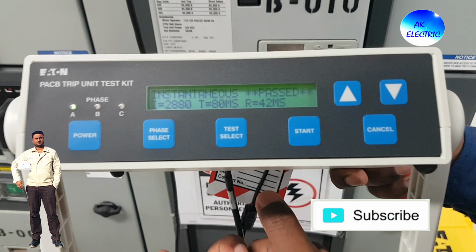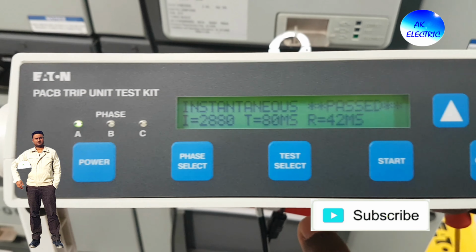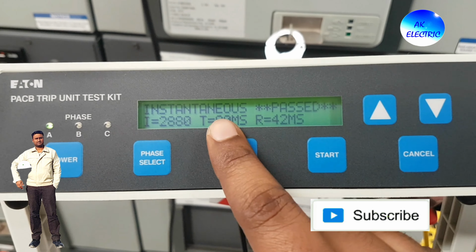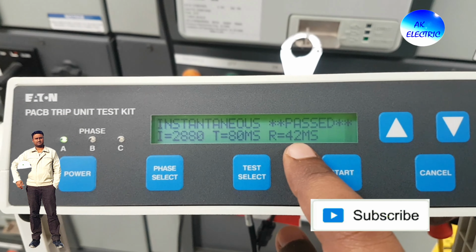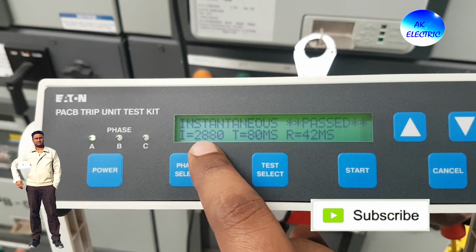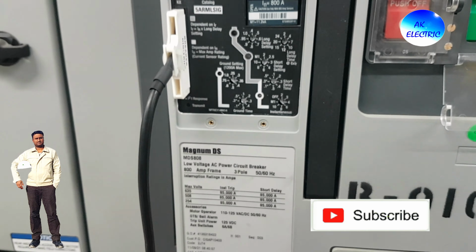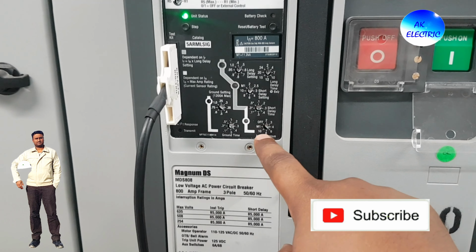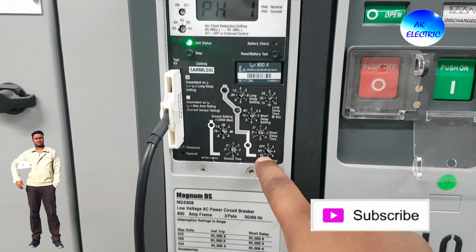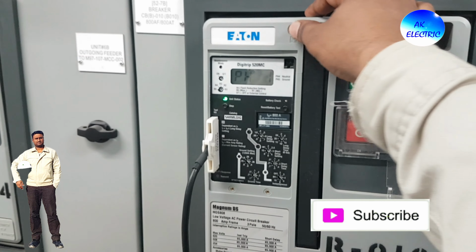Okay, see here, test is passed, instantaneous is passed. 80 milliseconds is adjusted and it tripped within 42 milliseconds. Current injected is 2880. Okay, in the breaker also you can verify. The instantaneous indication is highlighted, that means instantaneous operated and the breaker tripped. Okay, again we can reset.